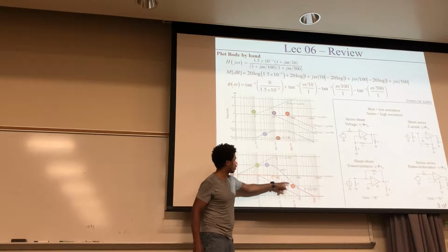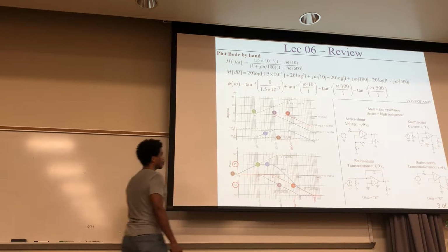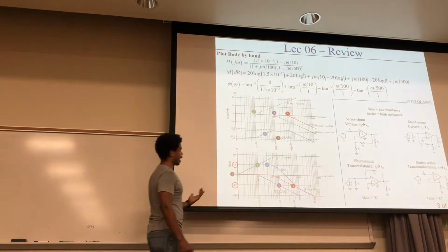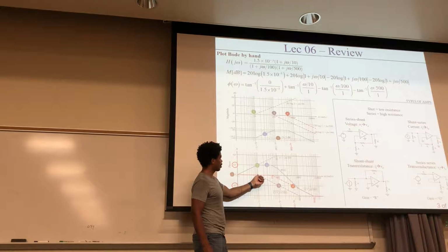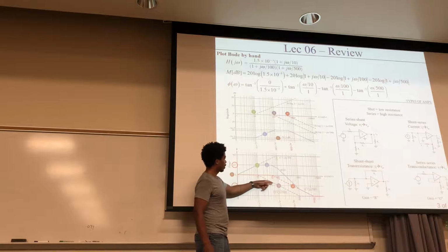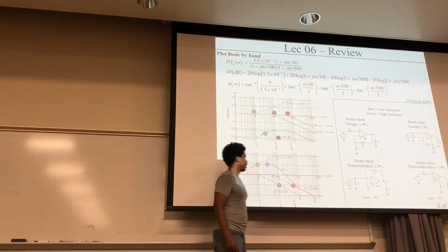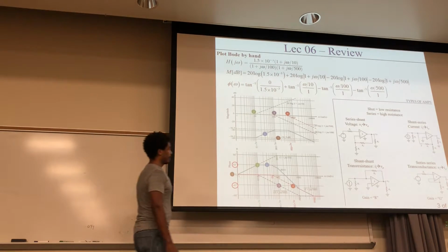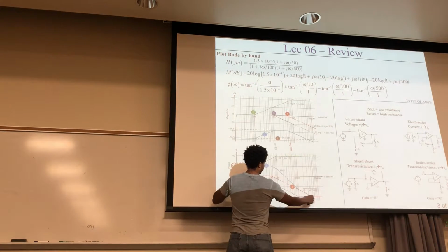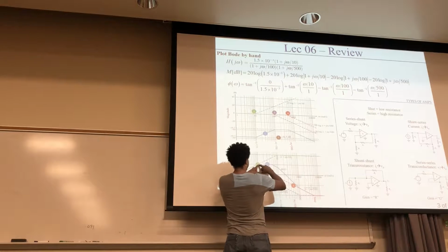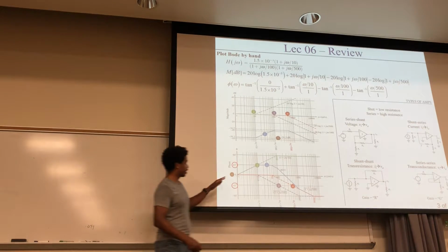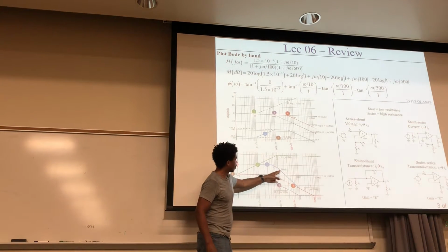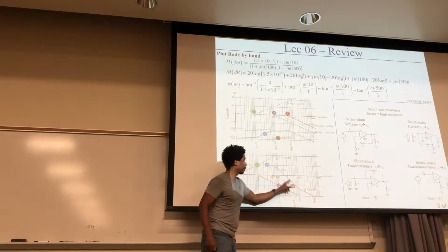Right here's minus 45, here's plus 45, right there. And then what happens is that if you're at 45, if you go up a decade, then you have your reflection, which asymptotes to 0. Going down here, this asymptotes to 90. Okay, so for each one, they go out and asymptote, and they go out and asymptote like that for each one of those. And then you add them together, and you get this blue curve right here with them all summed together.